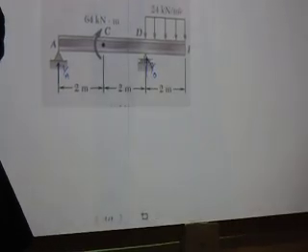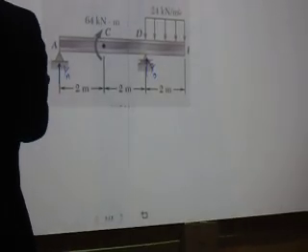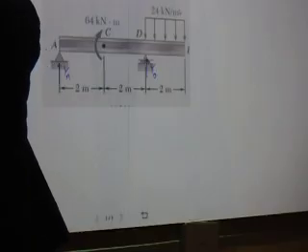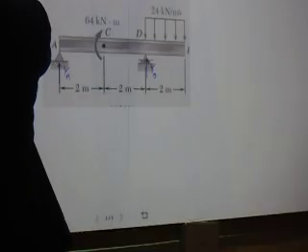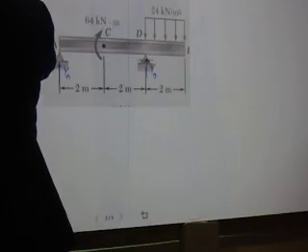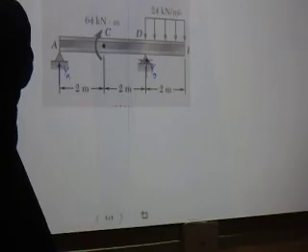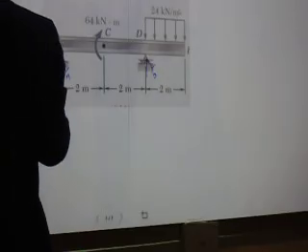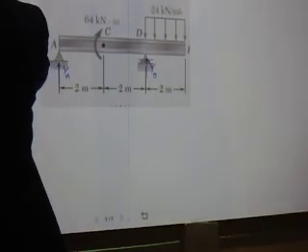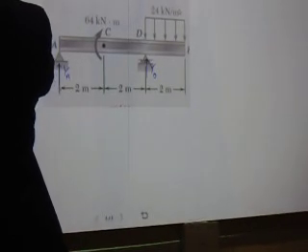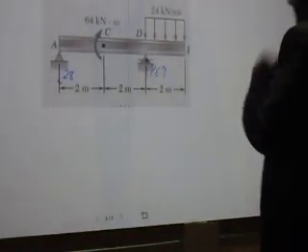Therefore, sigma Fy equals 0 equals YB, what's on YD, minus 28 minus 24 times 2. Therefore, YD is 24 times 2 is 48, 48 plus 28, this is 76 kilonewton. So this came to be 28 down. This came to be 76 up. Okay? Fine.